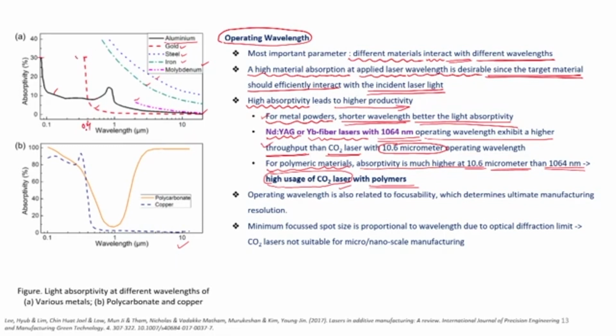It is showing very good absorptivity, 30%, but as you increase the wavelength the absorptivity is getting reduced. For molybdenum you just notice here the absorptivity is starting at the value of about 5 percentage for 2 micron, and it is getting reduced further.